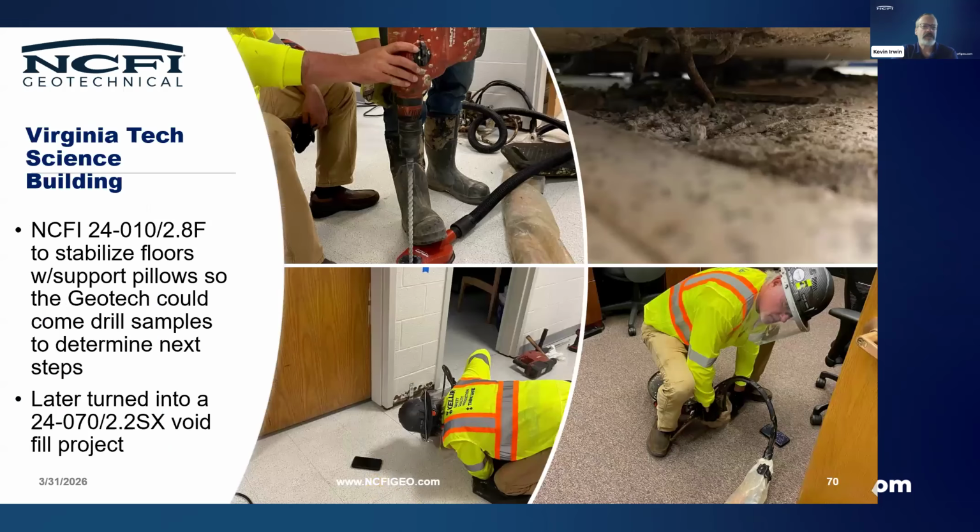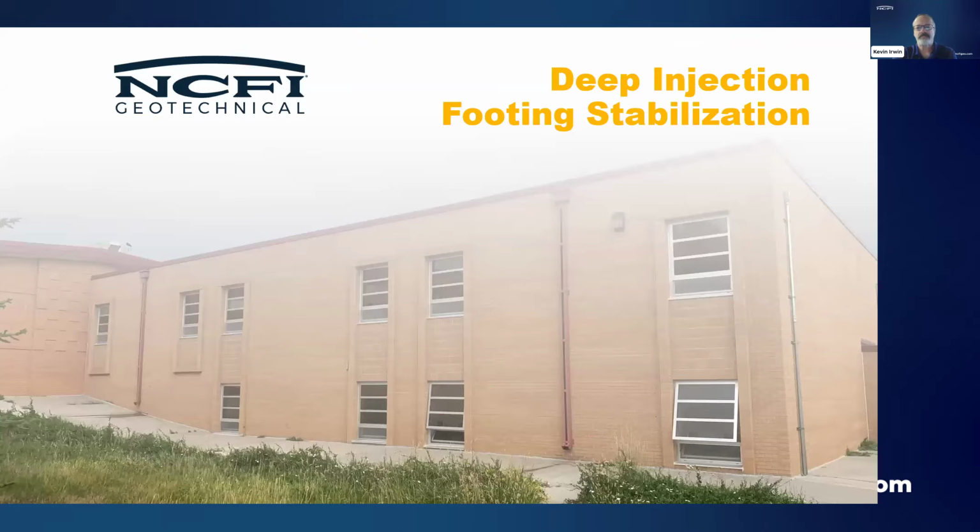Here's a stabilization. They shot to get heavy equipment into this location first. They already knew there was void underneath this slab. So they used the 2.8F to stabilize the slab so they could get heavy equipment in to drill and determine what the next steps are. Next steps turned out to be, hey, we're using 2.2 SX, which used to be the 070. It's a low exotherm void fill project.